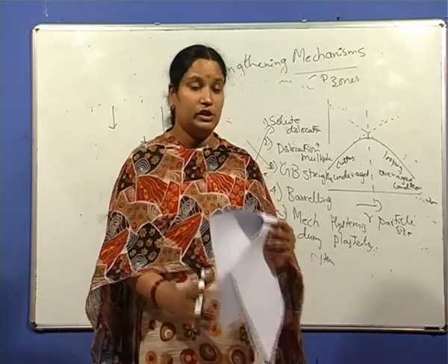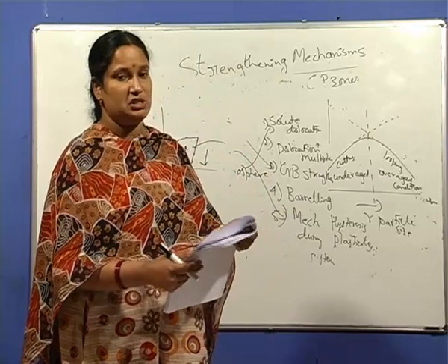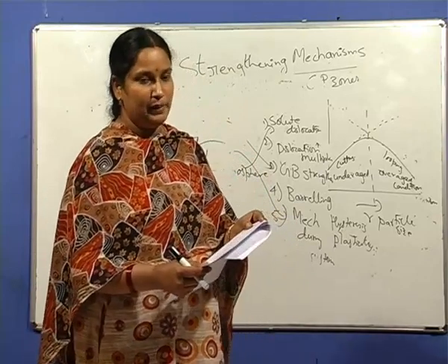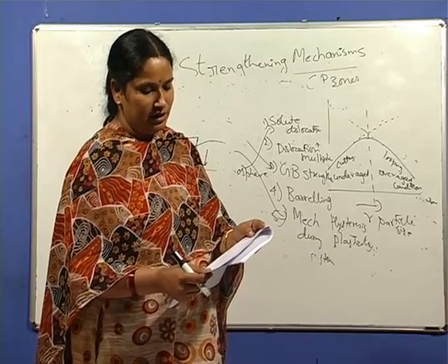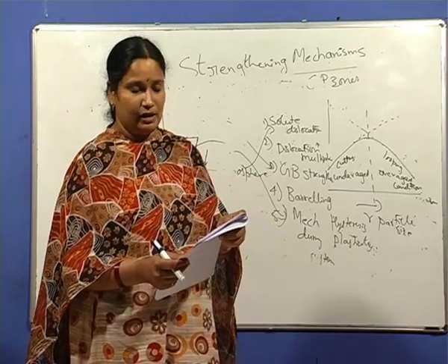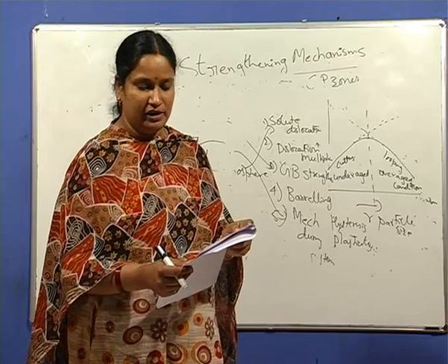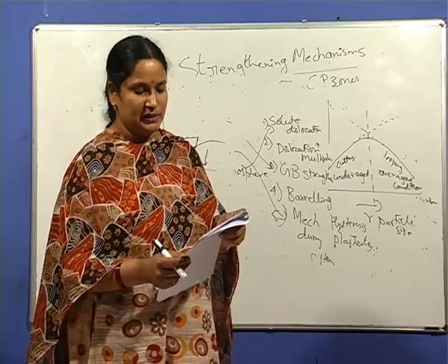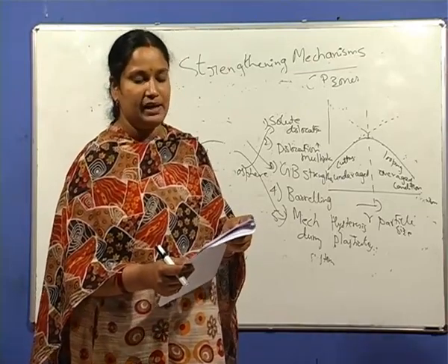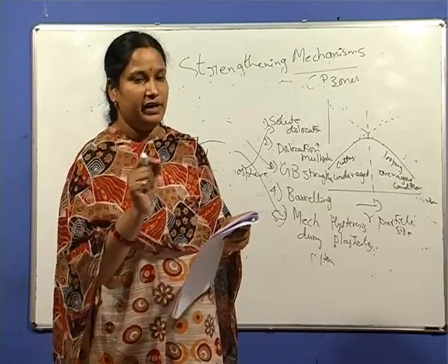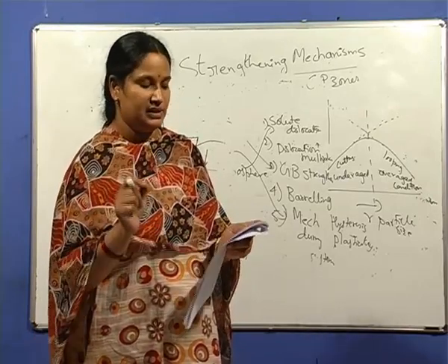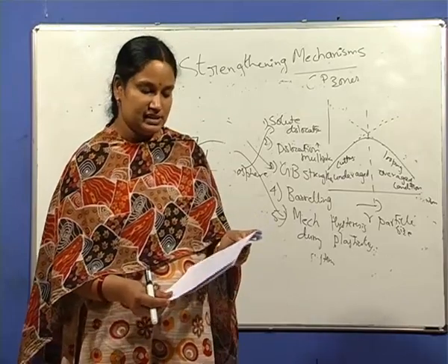Question number 42. In today's class, I have explained about the precipitation hardenable alloy. During low temperature plastic deformation of an under-aged precipitation hardened alloy, dislocations: A, climb to completely avoid the precipitate; B, loop around the precipitate; C, cross slip to completely avoid the precipitate; D, cut through the precipitate. When the precipitates are very fine, the dislocation cutting mechanism operates. So the option is D.